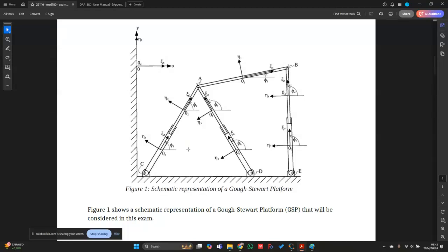If you, for instance, want to create a very simplified mechanism where you only consider the platform body, but you still want to model the actuators, then you would have a single body, body 1, and then connected to ground would be those relative translation drivers. So I can easily, from that situation, remove these bodies over here and just consider the combination of the linear actuators with the platform body, or the relative translation drivers together with the platform body. So I ideally want to use points A1 and then point C0 as well.